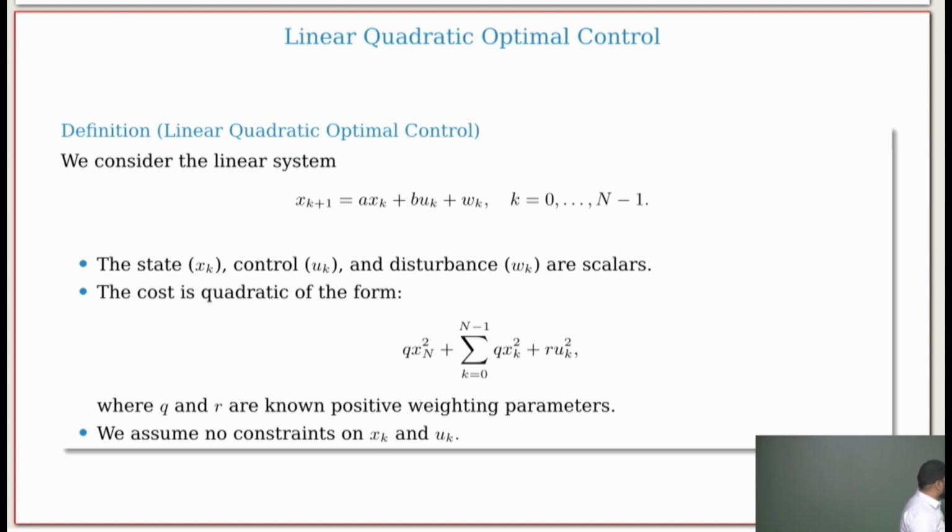And then what would be our cost model? In this case, we write this cost in this form. Again, this cost is dependent on the problem that we are going to solve. In this case, it's a linear control and quadratic cost problem. So that's how we decided the cost to be like that, because this makes sense for this problem. But cost could be different for different problems depending on the problem we solve. So here we have this quadratic cost that we assume.